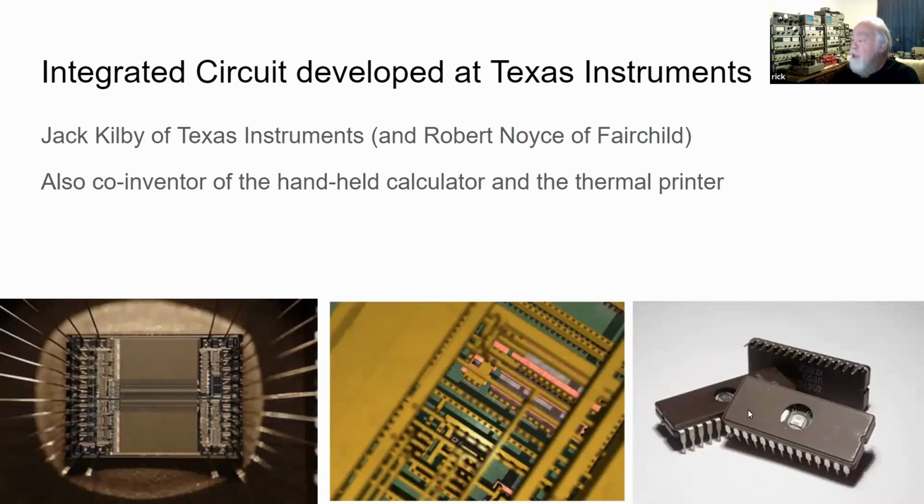And if you wanted to change the program, you'd have to completely erase it and then rewrite it. To erase it, you expose this chip to an ultraviolet light source for about 10 minutes. After that 10-minute period, all the bits are turned back to 0 so you can reprogram it again. That's the reason we have a quartz lid that allows the ultraviolet light to go through. It's so much easier now to change the programs and just rewrite them rather than having to erase and put in a programmer, then put it back in the computer.